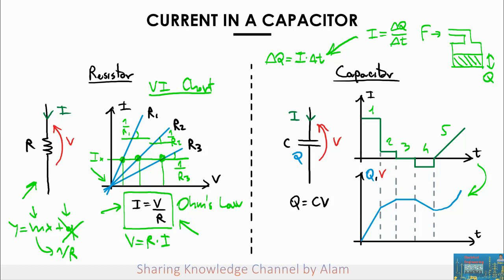This is pretty intuitive if you think about the hydraulic example, because this simply means that if you have a constant current, which means a constant flux of water going into your tank, the level of the water will just increase linearly with the time. So it will just go up like a straight line, and if you, for example, wait twice as much time, your level is going to increase twice as much.